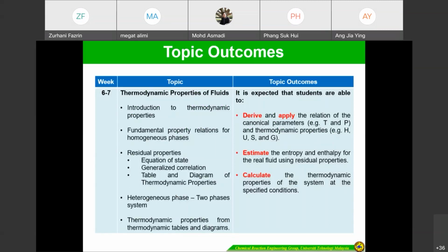Generally, the thermodynamic properties that we will consider are Gibbs energy, entropy, internal energy, enthalpy. To get the actual thermodynamic properties, you need these residual properties plus the thermodynamic properties at ideal gas conditions, I mean at the standard conditions.